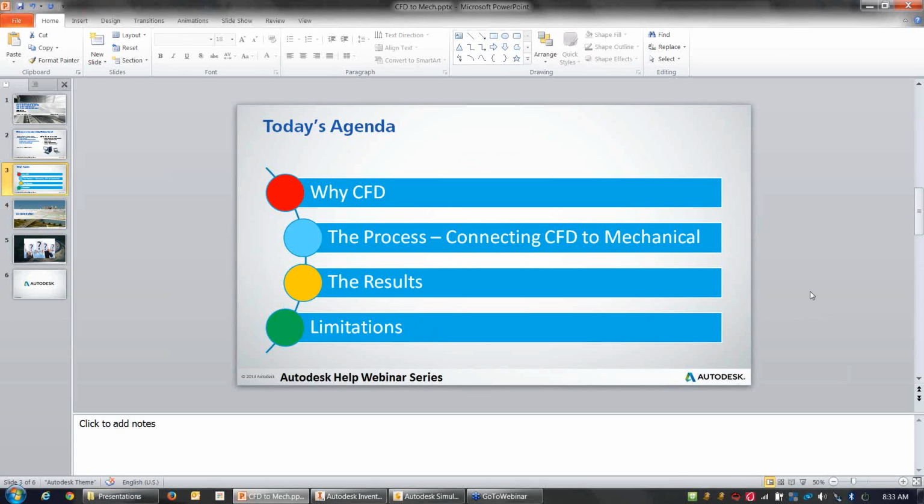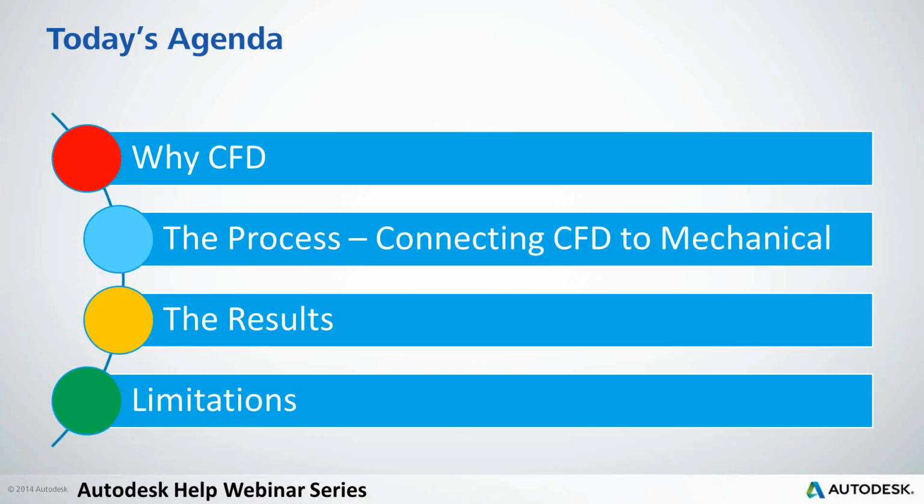For example, if you had a rubber diaphragm, we could not model how the change in fluid flow would affect the diaphragm, and then the deformation of the diaphragm affect the flow itself. So if we were varying the flow and there was a diaphragm being affected, changing the diameter of a tube or something along those lines, or even used for pressure flow, we cannot couple the deformation of that to the fluid flow.